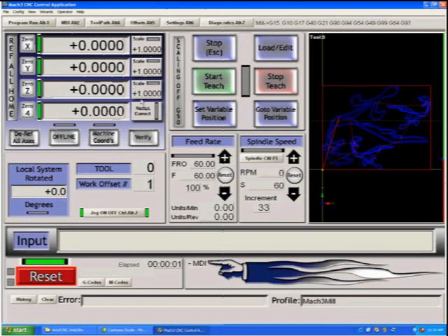Radius correction is used for 4-axis work, where you can tell the system the actual circumference size of the object, and it will correct the feed rate to create a toolpath that feeds at the correct rate on the circumference of a rotating object. Again, something that you can ignore unless you understand what they're for. We have dereference all axes, where we can tell the system that we're no longer homed. These LEDs turn green when we are homed.